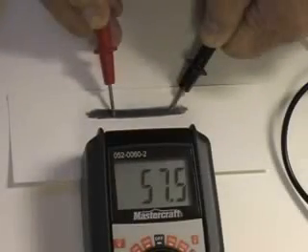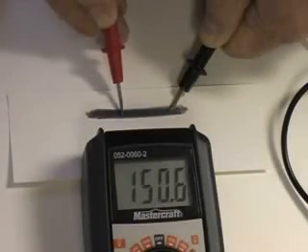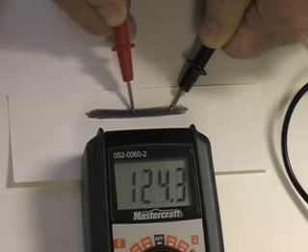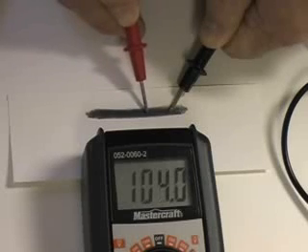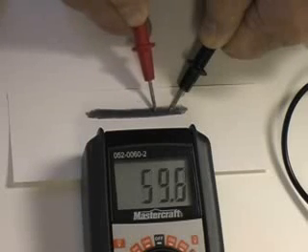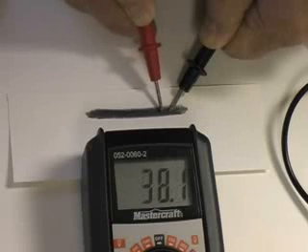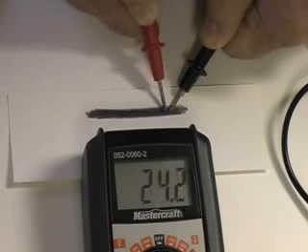The compound used to make small wattage resistors is similar to the material that pencil lead is made from, graphite. You can create a variable resistor with a heavy pencil line on paper. Touching the meter to each end of this line shows a resistance of over 150,000 ohms. Sliding the probes closer together, we see the resistance dropping into the 20,000 ohm range.